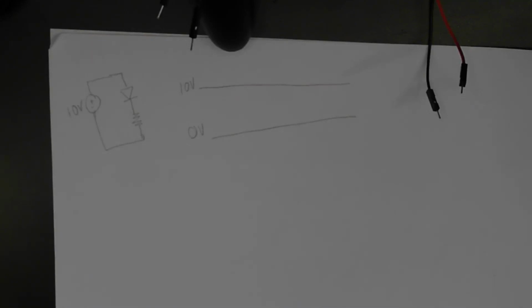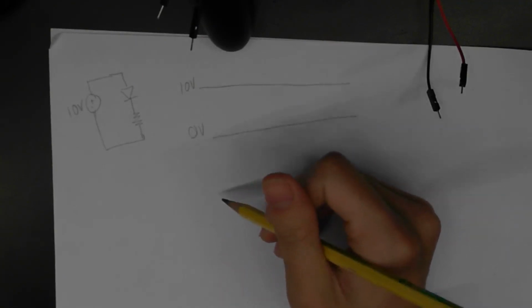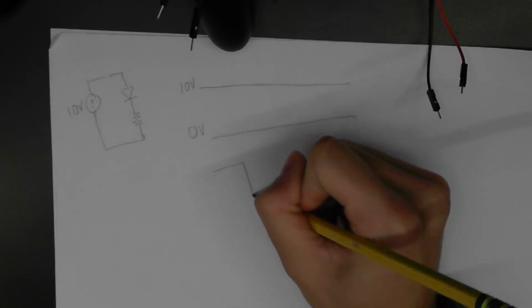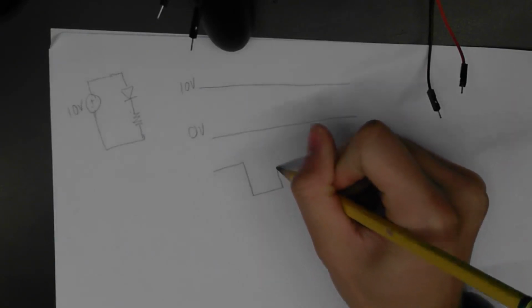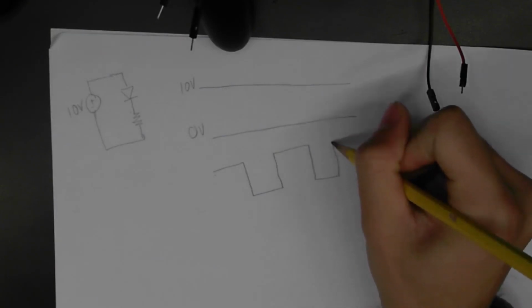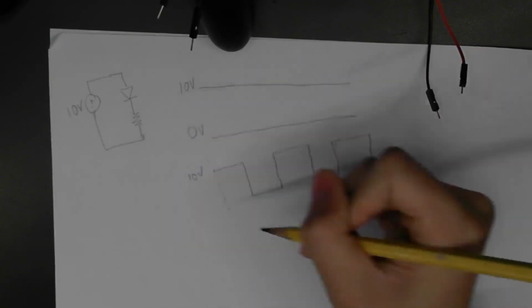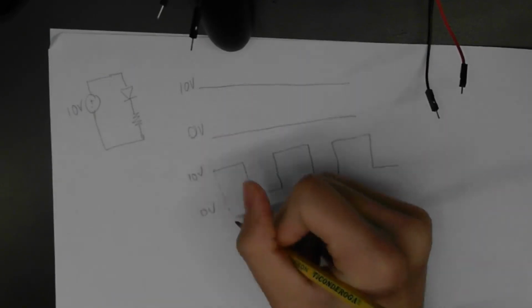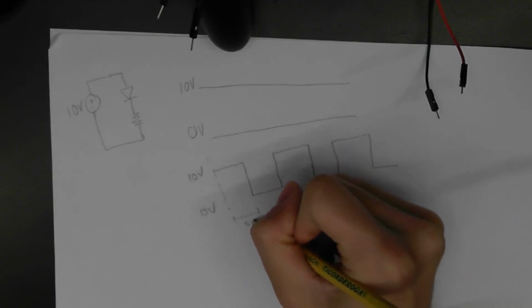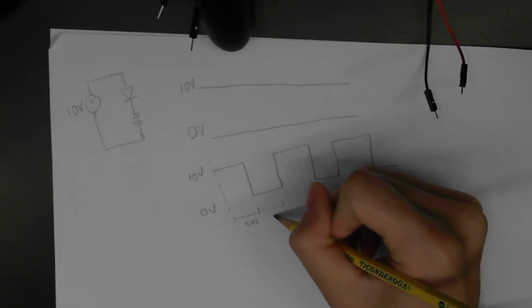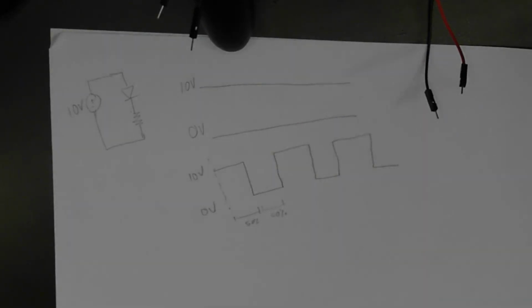PWM comes in. And to apply it, I'm going to do a very simple PWM by, let's say, having your electrical signal, in this case, be at 10 volts half of the time, and then at 0 volts half of the time, and repeatedly over multiple cycles. And this is your basic concept of PWM, 10 volts and then 0 volts. For 50% of the time it's on at 10 volts, and for another 50% of the time it's off at 0 volts.